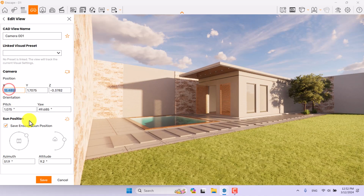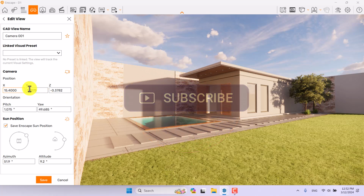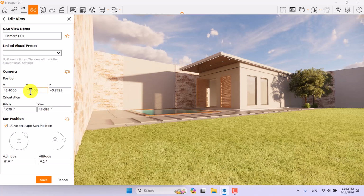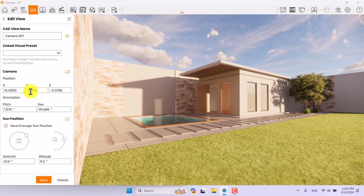My X position is my X coordinate in SketchUp. So 15.4 is good, and you can see small changes when you adjust them. The Y option is related to your eye height. When I change it to 1, it goes down, and when I change it to 3, it goes upward. So it completely depends on you. 1.6 is the standard number.